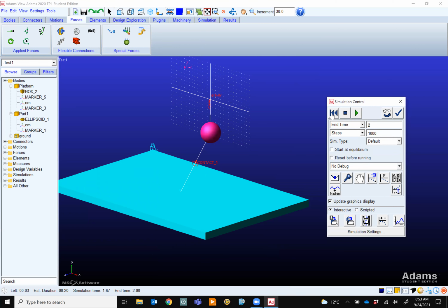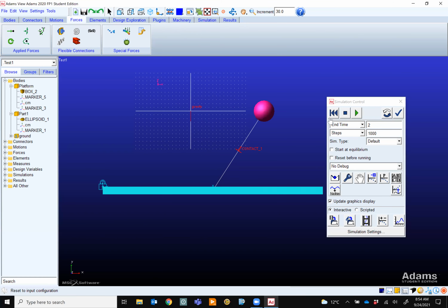So at the very beginning when you build your model, do not create any contact. Again, as I said, it makes the model nonlinear, it makes it messy. Do it at the very, very end, or maybe never do it for this mechanism that you build. I'm just focusing on your project. For other things, yes, do whatever you want. So you can look from the side view as well. Let's say you finish the simulation. Let's run one simulation together.